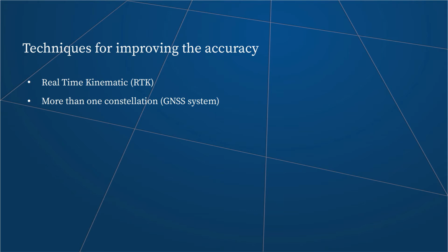When a receiver tracks more satellites, it benefits from increased availability and it has more data to pick from, and it can even reject some of the satellites which are at low elevation above the horizon. All this leads to better accuracy overall. All modern satellites transmit their signals at 2 different frequencies, and when those 2 signals with different frequencies travel through the ionosphere, they experience different delays.